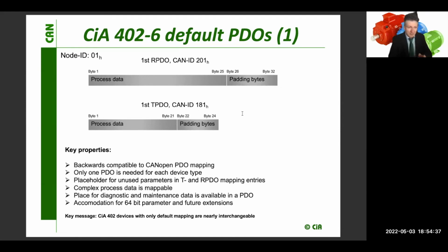So it was decided to encode only certain sizes. The next after 8 will be 12, then 16, 20, 24 and so on going forward. So the data link layer adds padding bytes to fill my payload up to the next supported message size. So that's important to know. Thus, you cannot recognize how many bytes you really have.